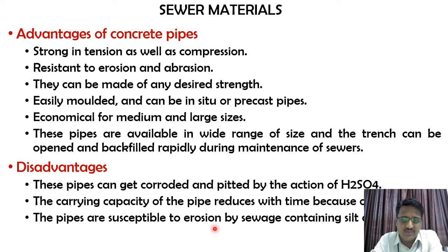Next, the pipes are susceptible to erosion by sewage containing silt or grit. Any inorganic material that is there can, over a long duration of time, act as an eroding material for these concrete pipes.